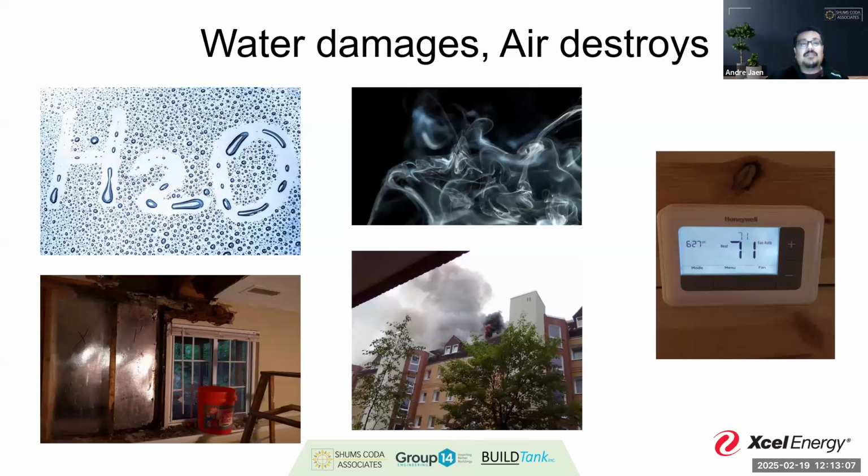You know full well that if you have water intrusion, whether that's from a burst pipe or whether that's because something is getting in past that water resistant barrier, as it freezes, it expands. As it expands, it creates more of an entry point for more water, more mildew, right? And it becomes a feedback loop. At the same time, our air barriers are sort of doing similar things. That's why I say that they have this overlap like a Venn diagram, but functionally they're designed to compartmentalize buildings, and that's tied in with that thermal envelope.